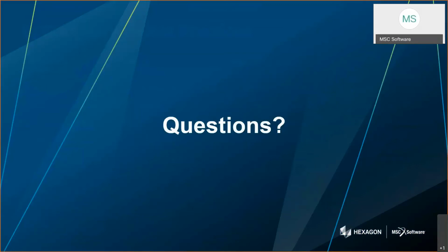All right. So we've had a very lively Q&A over here, and we're probably not going to be able to get to them all, so I apologize ahead of time. But some of the really cool ones that came out, I'll read them to you, and you can answer for me. So the first one is, let's say you have a solid piece of geometry. Can you actually draw on that solid body and create geometry, not just import CAD? Absolutely. Apex has a full suite of sketching tools. And it also has things like push-pull, some of the direct modeling functionality, which you can use to create 1D, 2D, or 3D geometry, either freestanding or connected to your CAD model that's come in.